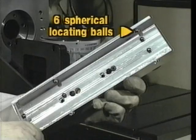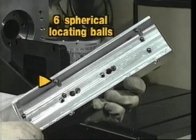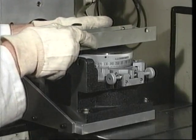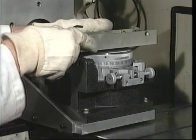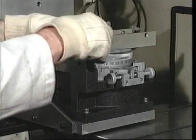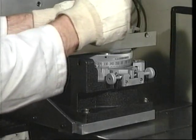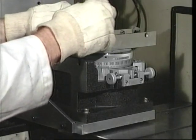A kinematic cradle was constructed to support the straight edge with maximum positioning repeatability during the reversal process used for straightness of motion measurements. Although the straight edge won't be repositioned between the steps in this squareness measurement, we will use the cradle for supporting the straight edge. The kinematic cradle is attached to the index so that it is nominally parallel to the x-axis.